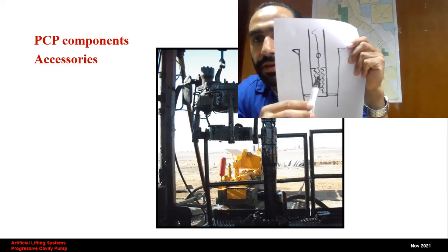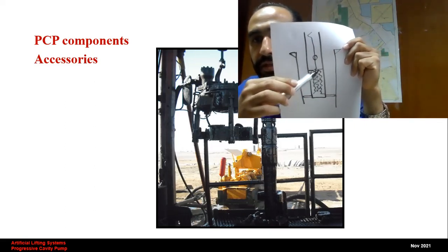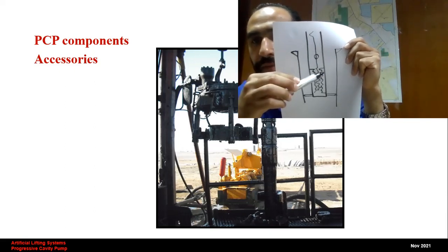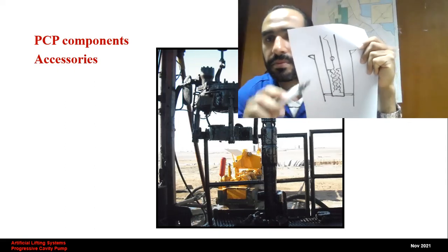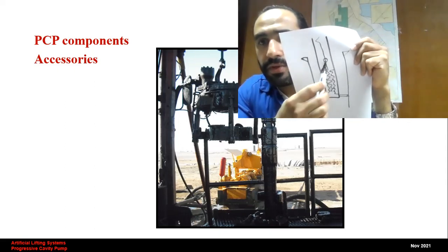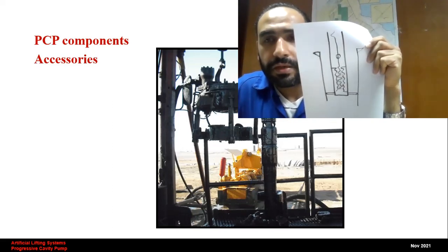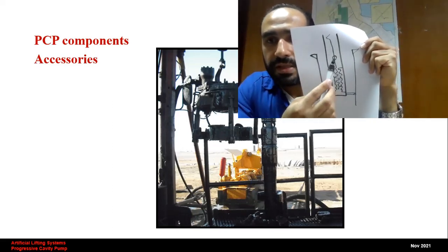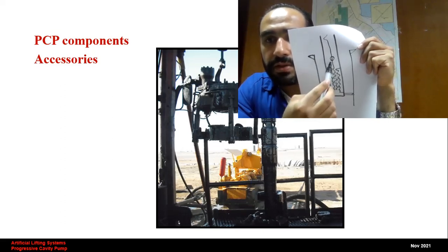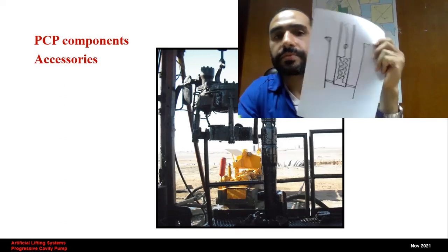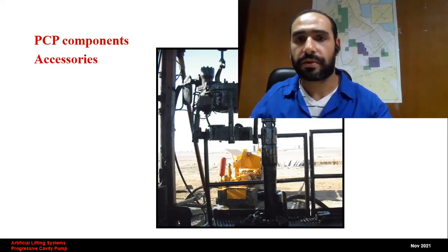So this now is blocked, and the tubing is full of fluid up to the surface. Those are the 30-40 barrels we are taking care about. And this is the tubing drain. Actually, it's normally placed one joint above the stator to provide the necessary connection to the casing to drain the fluid inside the casing. So that was the tubing drain.